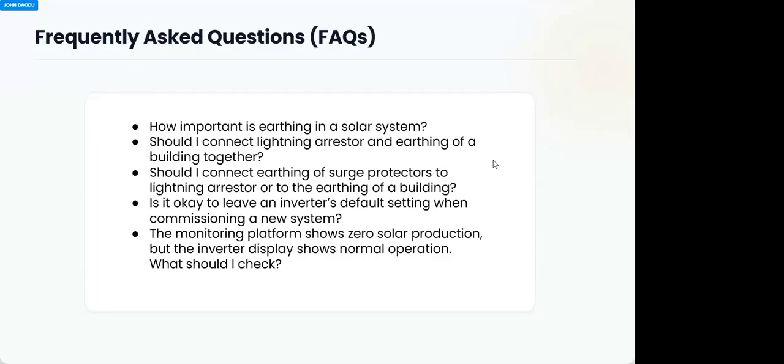Okay, let me take it again, sir. I say, what is the proper order of connecting surge protector, breakers, and AVR? Okay. The proper order of connection of surge protector, breaker, and AVR. AVR is automatic voltage regulator, which is a stabilizer when it comes to AC circuits. And surge protectors, we know what they are. They suppress spikes and all that. They are terminated across the supply.